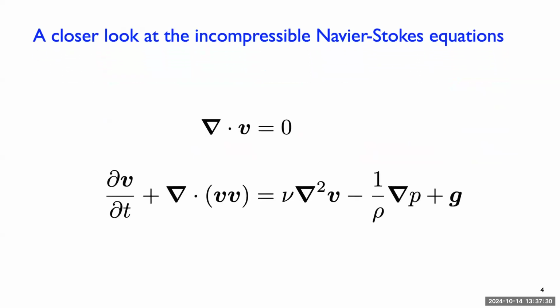So these are Navier-Stokes equations for an incompressible and isothermal fluid. So we have a conservation of mass, which is the same as conservation of volume. We have an inertia term, a so-called convection term. These are viscous stresses, these are pressure stresses, and then gravity. So these are surface forces, these are body forces. This is essentially Newton's second law, mass times acceleration equals the sum of surface forces and body forces, and the surface forces have a viscosity component and a pressure component.